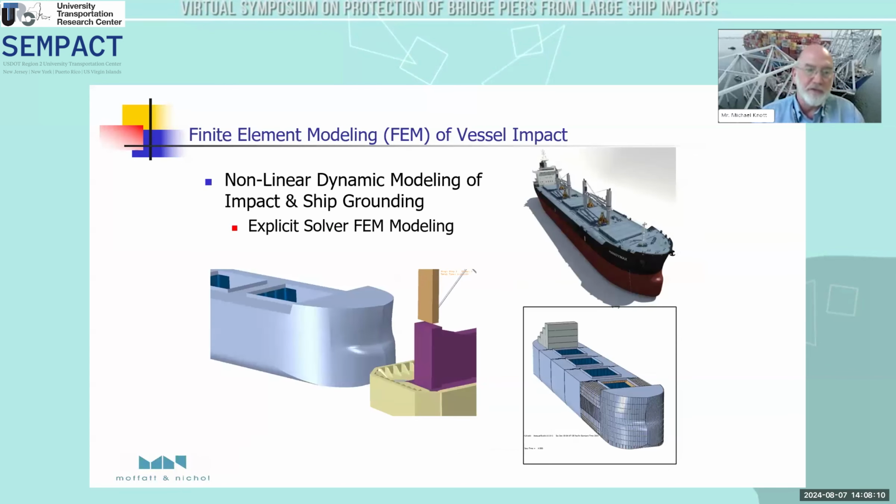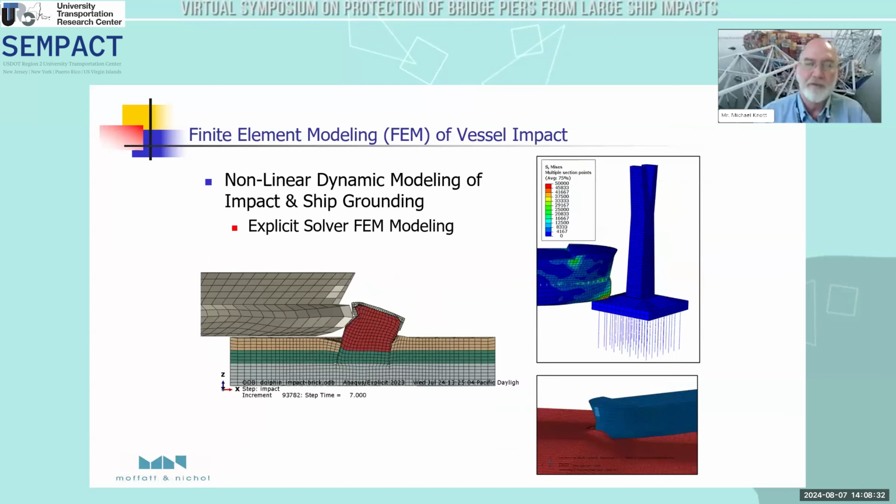These days, we can use some fairly advanced models. We use explicit solver finite element modeling. Just to show a little animation here, this is a small bulk carrier impacting a suspension bridge. And as was mentioned by a previous speaker, we actually found a little bit of bounce back from the ship hitting the bridge pier.